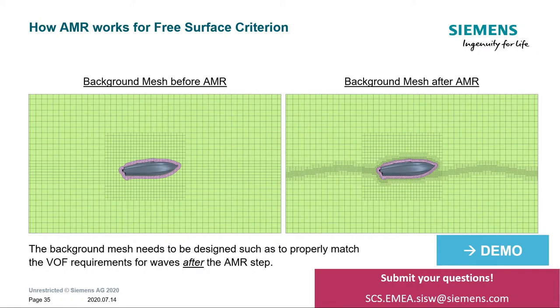An important point I wanted to highlight here is the fact that adaptive mesh refinement is isotropic only. However, if we start already at the beginning with an anisotropic mesh, then the refinement will ultimately provide an anisotropic mesh.